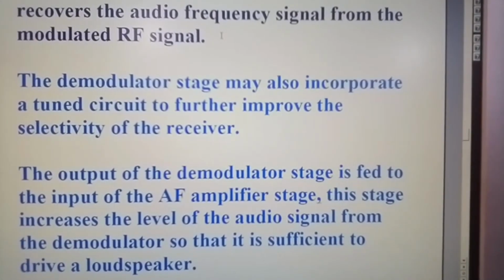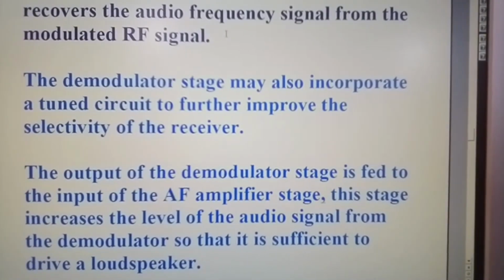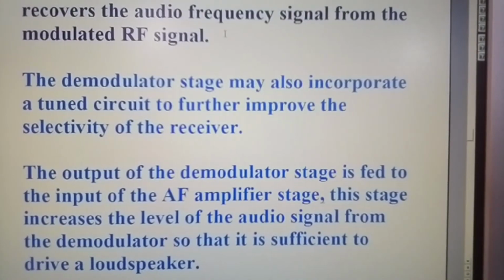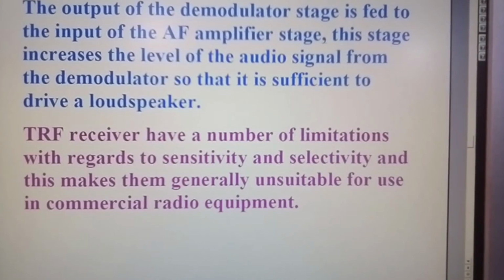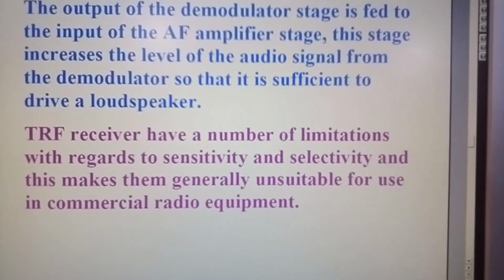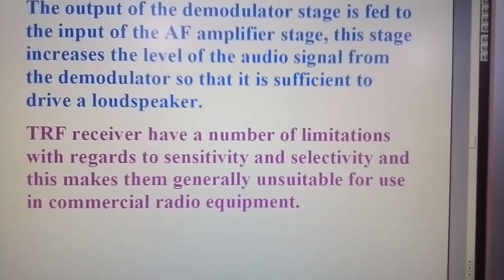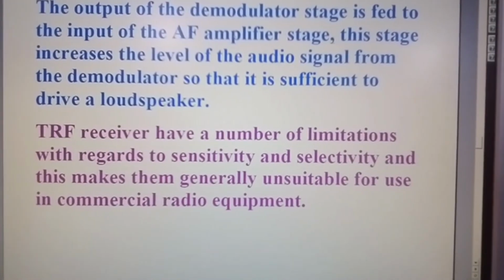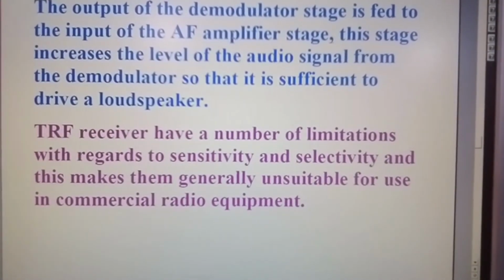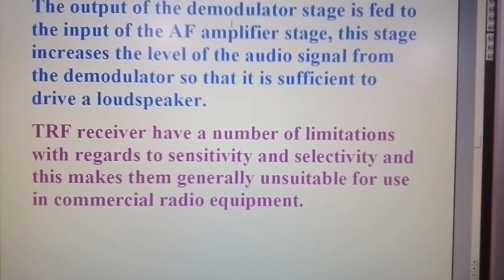This stage increases the level of the audio signal from the demodulator so that it is sufficient to drive a loudspeaker. TRF receivers have a number of limitations with regards to sensitivity and selectivity, and this makes them generally unsuitable for use in commercial radio equipment.